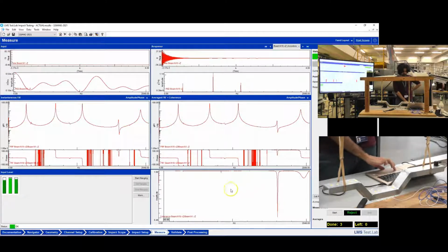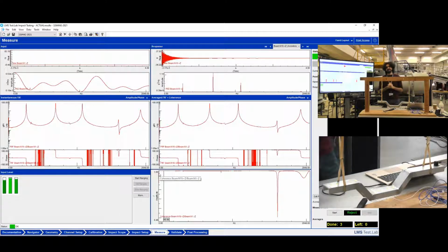And what you have here, in this last plot, is something that is called coherence. Now, coherence is an index. As you can see, it goes from 0 to 1. In this case, 0.446, but it goes from 0 to 1, and it represents how much of the output has been caused by the input. So it says if I have captured the entire cause of the output as an input.